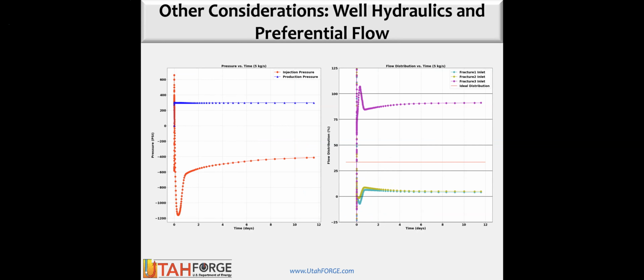But the important thing that you bring up, Mukul, is essentially with those three open zones, we have some pressure drop across those perforation zones and the open hole toe. And so what you're seeing here in this slide, this is provisional also. I mean, this, my intern just handed me these last night. But what you're seeing here essentially is pressure on the inflow side and on the outflow side. So on the outflow side, if we fix the pressure at 300 psi, I'm mixing units, I apologize, we keep the fluid single phase. If it's coming up at about 200 C, and we're putting fluid in on the order of 25 C, we get a pretty strong density drive just from the weight of that fluid. So we don't need a whole lot of pumping power pushing fluid in.